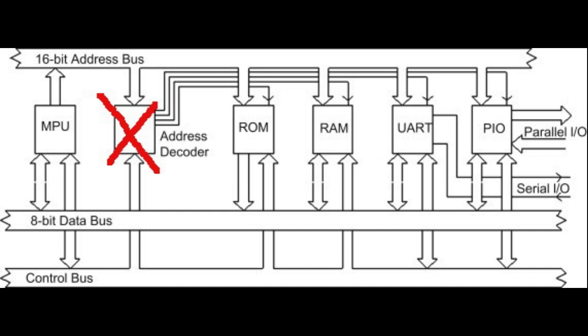What may happen is that the ROM never gets selected. So when the CPU starts executing code, it goes to the ROM location to read instructions, but the ROM never gets selected, so the data bus basically reads like noise, and the CPU just gets confused and does nothing, or gets stuck on an illegal instruction or something else.